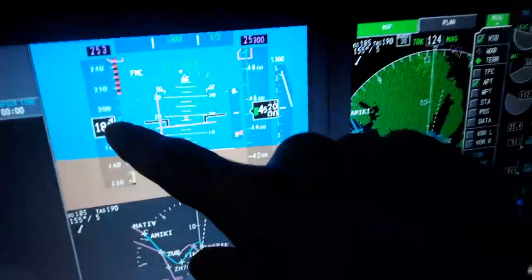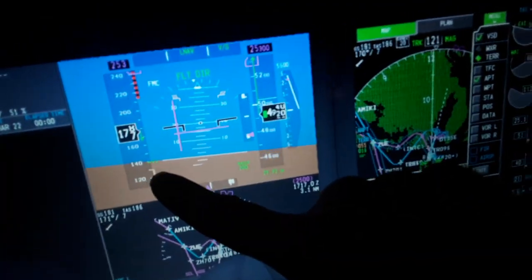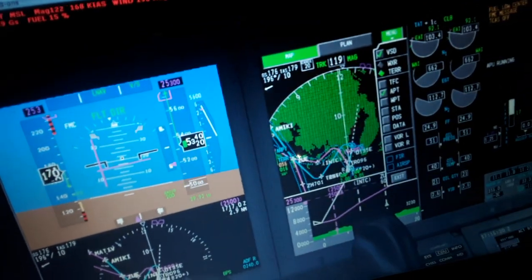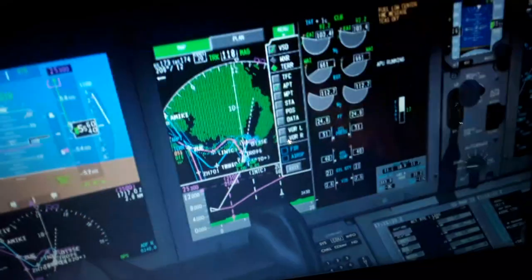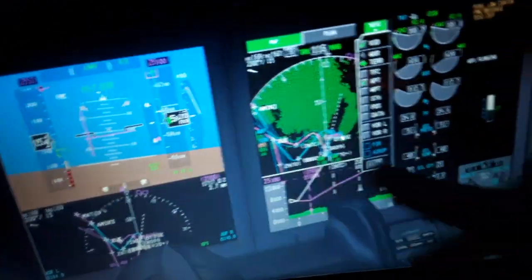So you can see here we have the airspeed indicated 180 knots. The pitch attitude 20 degrees. So the stall speed, we need to avoid yellow and red indications. 5,000 feet above sea level, 5,000 feet per minute the rate of climb. You can see here the indication from the engine stages also. So mostly important the airspeed.